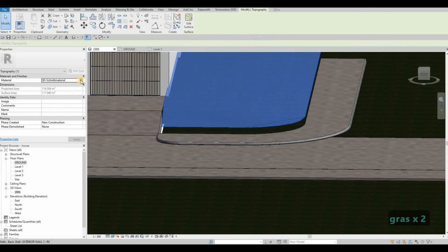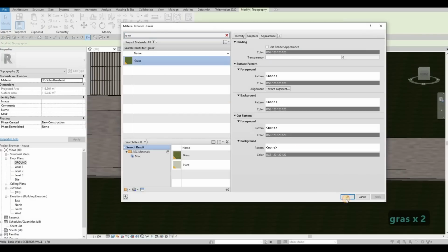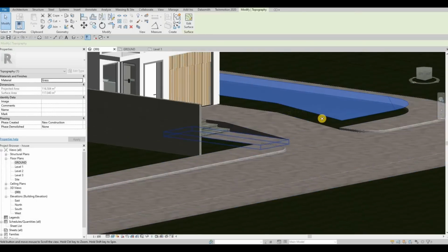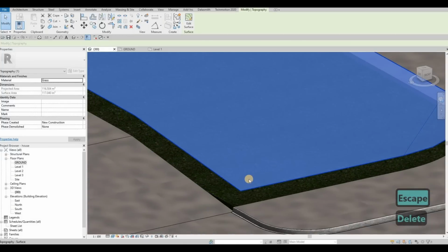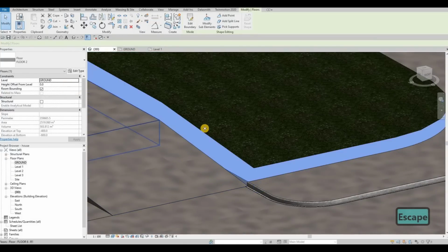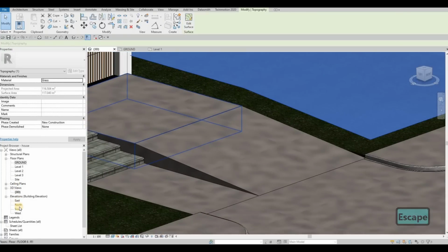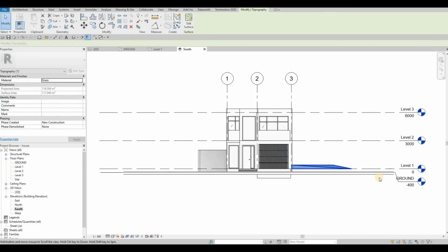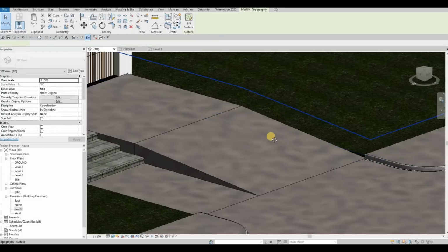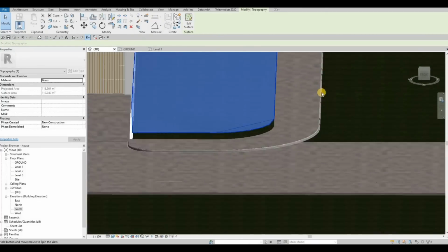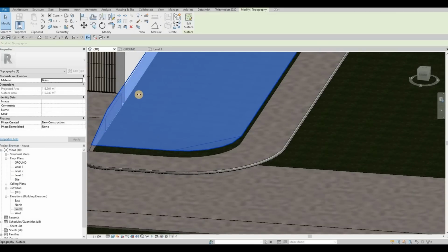It's much more control. That's why we're doing this. And then we could edit this one. So we could delete this now. Edit. We need to know what's the, so level is ground, and then the ground south elevation is -400. So we need to change some of the points that we created to -400 here, but connected everything here afterwards.